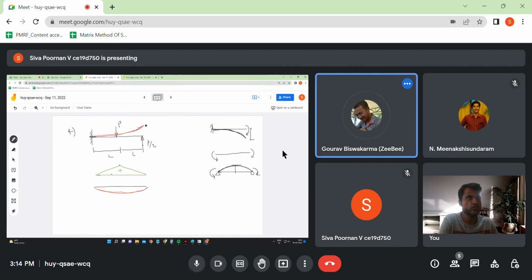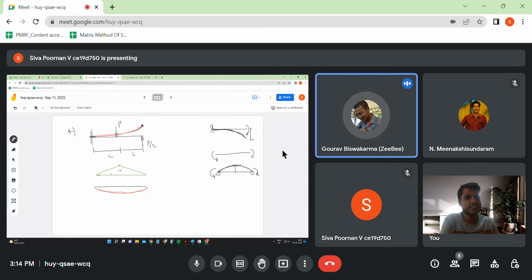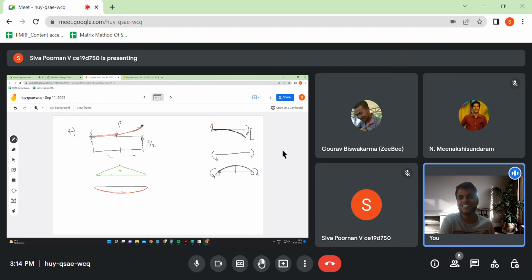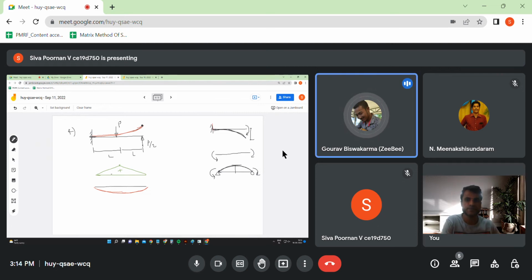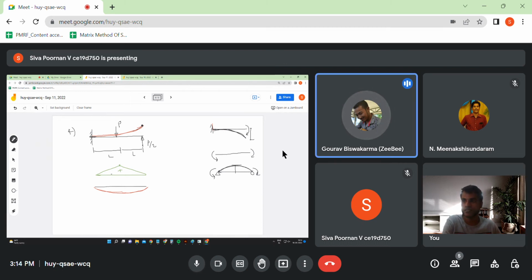So the deflection is also maximum slightly towards the right of the load. I think so. So where are you saying the deflection would be maximum? Slightly right of the load, mid load. Actually, I'm thinking of this question as a propped cantilever from the starting. A propped cantilever would have an entirely different thing, because we don't know the support reaction. When I saw this question, I solved it as a propped cantilever.